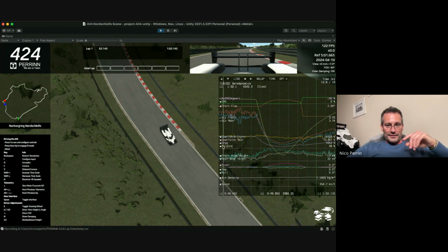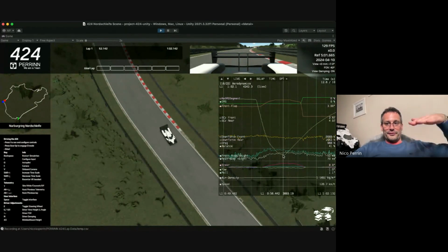And the reason we do that, as I said, is that now we look at the balance, the aerodynamic balance. You see this trace here. Because the car is moving up and down with ride heights, you see the ride heights on the cursor. We are 20, 33, but in mid-corner, the car goes to 50, 70. And as I just explained, if we wouldn't move the flap, the aerodynamic balance would go from being very much to the front, and in mid-corner, it would go to the rear. So by moving the flap, we're reducing these effects.